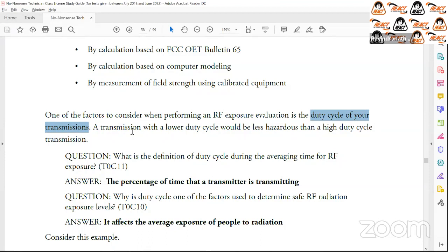If they tell you 1 minute on and you need to have 5 minutes off, if you only go and run that for 5 minutes continuously, basically you have exceeded the duty cycle rating of that device. In other words, you might mash it up faster by exceeding the duty cycle. So think of duty cycle as how much of the total period that you're actually using it for, right?